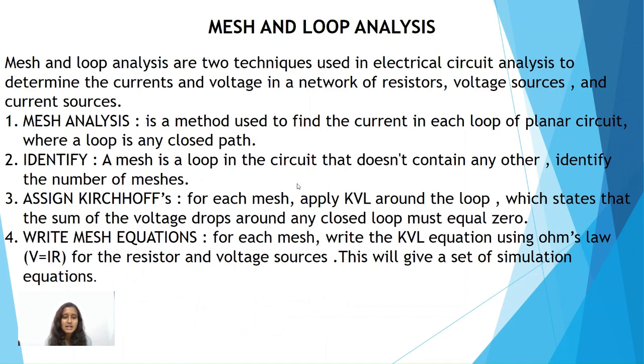Mesh analysis is a method used to find the current in each loop of a planar circuit, where a loop is any closed path. A mesh is a loop in the circuit that doesn't contain any other loops. First, identify the number of meshes.